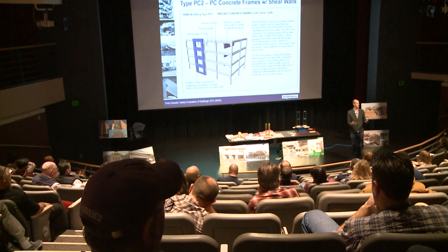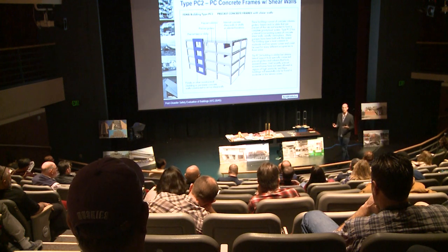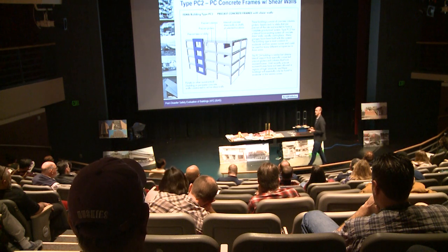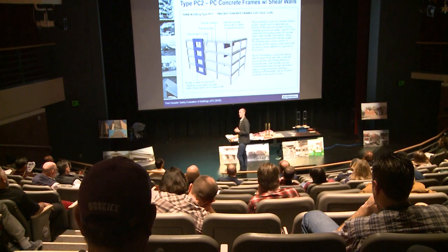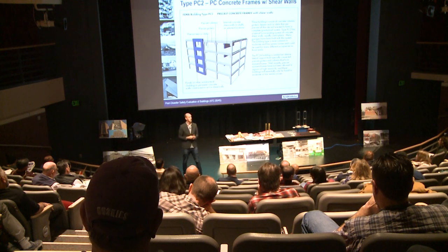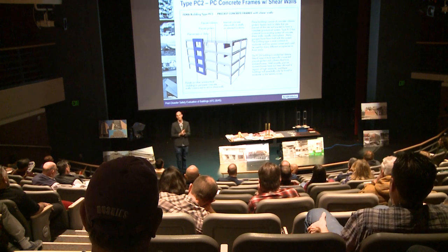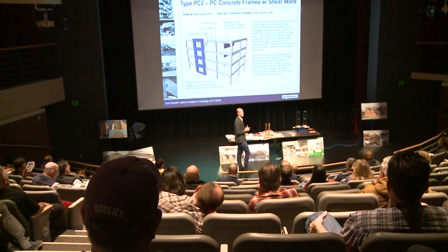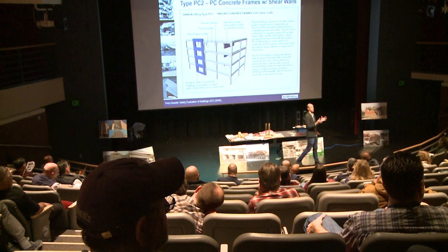Steel, the material itself is inherently ductile, just like our paper clip. The configuration of it generally should be, particularly with modern requirements, but as we learned from that 1984 Northridge earthquake, it can fracture welds in a non-ductile manner. What about masonry? So unreinforced masonry, we've seen a bunch of examples of that, are definitely non-ductile and it's heavy, kind of the worst of the worst.